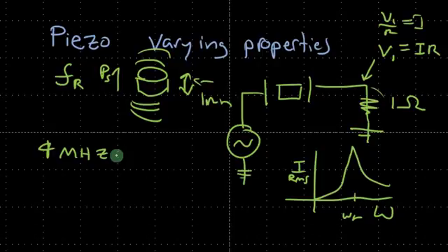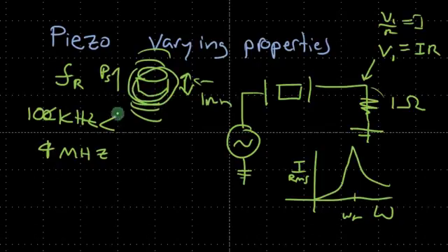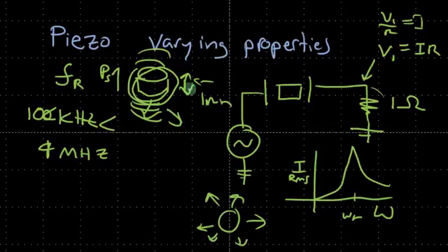You're also going to get a lower resonance, which is going to be in the kilohertz region, which is going to be greater than 100 kilohertz. So usually greater than 100. But that is the longitudinal vibration. So if you had vibration around the radius, it'd be sort of extending in each direction. If you had your disc, looking at the disc from the top, the vibration would be like this, radial, versus vibration here where we have vibration in the thickness. So we're looking at the top. The vibration was sometimes 4 megahertz, 5 megahertz. There's so much variation.